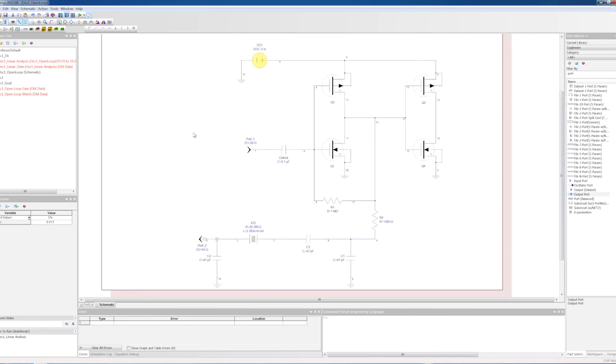So I've duplicated my circuit here in Genesys, and I'm just using a pair of NMOS, PMOS transistors here to simulate the inverting gate. I've also put another pair here as an output buffer. But this is the main pair here that's going to actually be doing the oscillation. We have a 1 mega ohm resistor here tied between the input and output to bias this gate into a linear state. We have the typical feedback network here with the crystal in it for a Pierce oscillator.